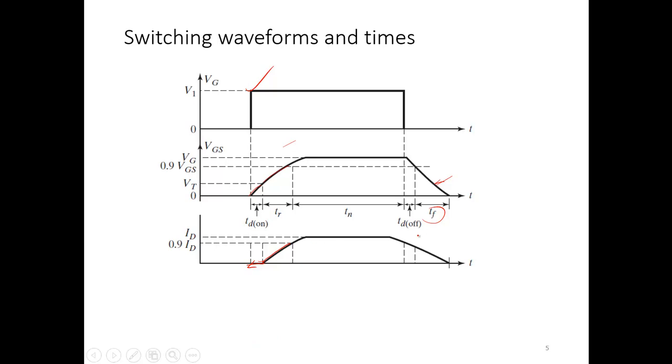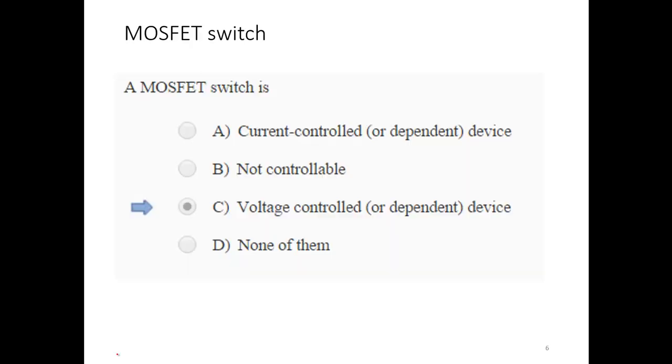By this definition you can find out the maximum frequency you can operate at. If you look at the catalog, the manufacturer will normally specify the rise time and the on time. But the on time depends on the operating condition, what frequency you're operating at. The delay time and rise time are decided by the device itself, and the fall time also depends on the circuit and what behavior you have.